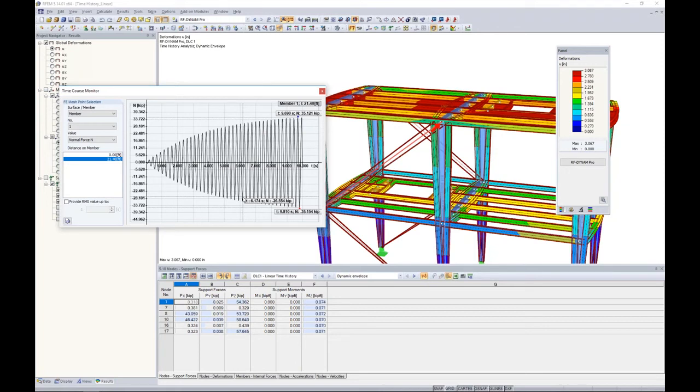That tension-only member was replaced with a truss member that can take both tension and compression. So the question is, well, how could my structure possibly look different in terms of my natural vibrations if I were to account for the failure of these tension-only members? So we want to move on to a second natural vibration analysis study where we deactivate these failed tension members.